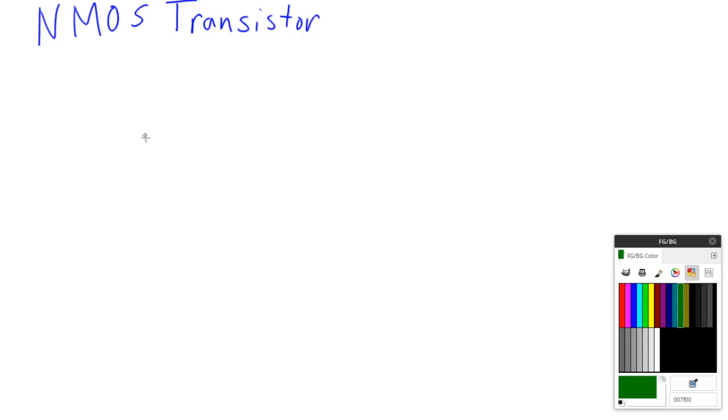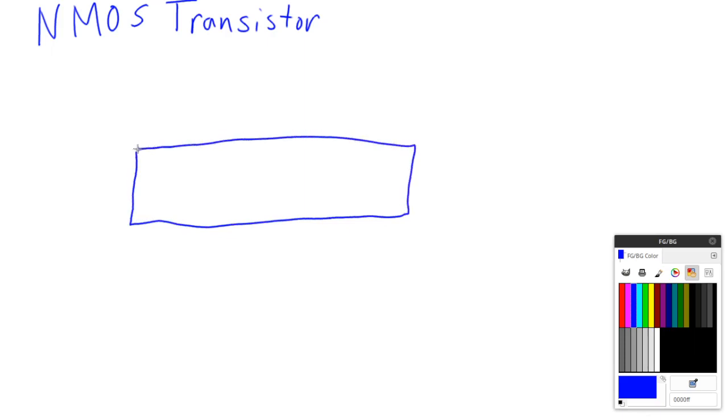So let's suppose that we've got a big old hunk of silicon. It's not silicone. Silicone is a rubber, right? Silicon is the elemental form of, well, silicon. And we put some chemicals in it, or dope it, such that it has a deficiency of electrons. A deficiency of electrons just means that it has a bunch of something called holes, or spots that electrons could go. And so we call that a